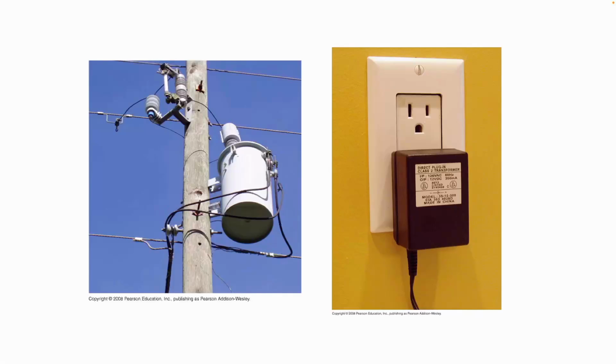However, all of these devices expect 5 volts. What's the voltage that comes out of the wall? 115, 110 to 120, right? We usually say 115 average. Okay, but 120 volts max, RMS max. And so the brick is responsible for taking that from 115 volts down to 5 volts and also rectifying it into DC.